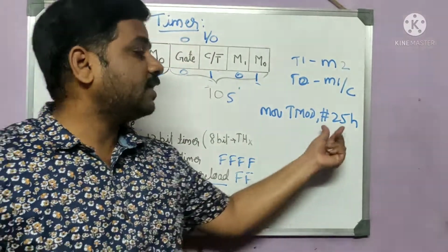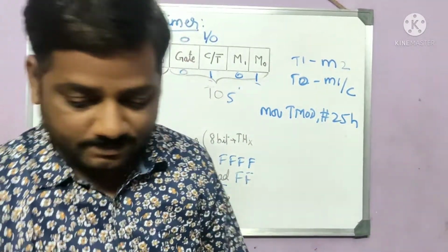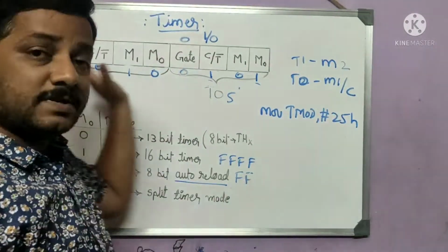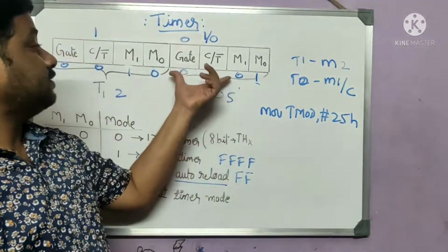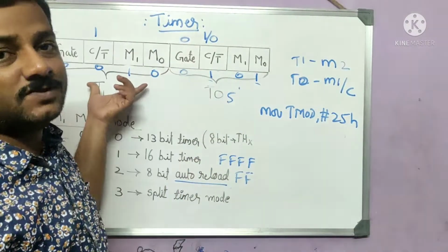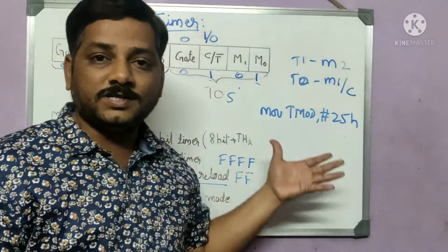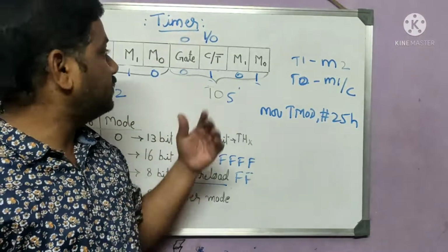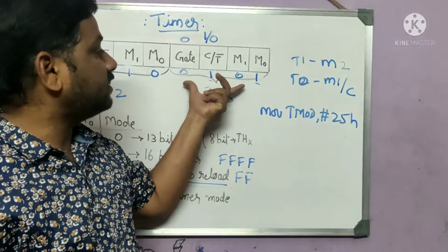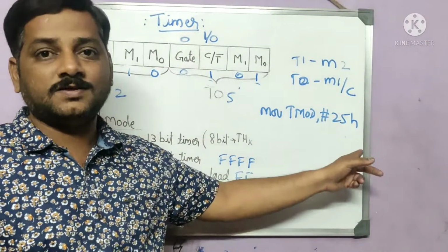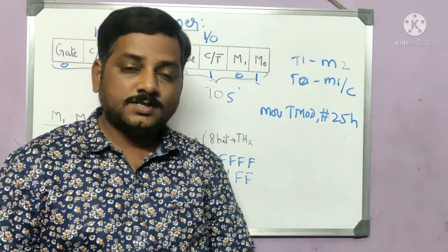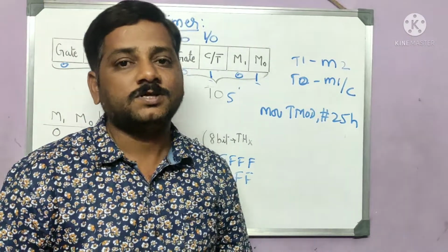So you cannot learn these numbers by heart. You never learn that number by heart. You just remember this 8-bit register. Okay. And also I will tell you, if you just remember these 4 bits, the same 4 bits will be there for the other higher nibble. So remember this, and based on our requirement, the bits will change. And after writing the bits, you just write that decimal number, that number in this line. Okay. This is how the TMOD register will be used.